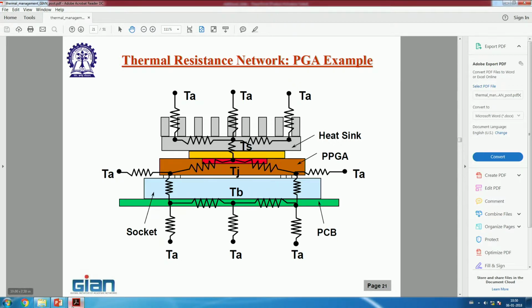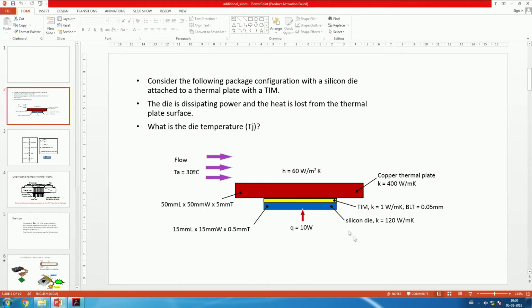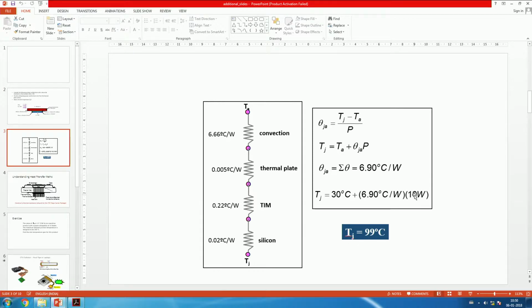So, what I will do, and this is what I was talking about before, a drawback of the thermal resistance method is that I assume the entire heat is flowing in this direction, but it may turn out, by the example that I just talked about, just the numbers that I picked, that it is not 10, actually it is 8 watts that is flowing through in this direction. Okay, fair enough. So, I should multiply this by 0.8, and that gives me a little bit of headroom. Or in other words, I would say 10 watts is the limit of the heat that comes to the top, which is 80% of the total. So 10 by 0.8 is the amount of heat that you can put in.